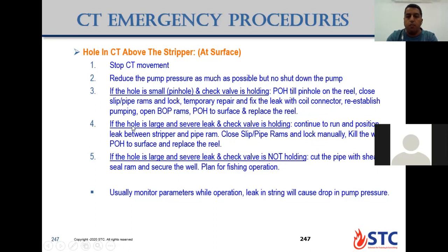Number 4, if the hole is a little bit large and there is a severe leak, and the check valve is still holding, so you will not have any more buildup of pressure at the surface, but you have a leak at the surface.